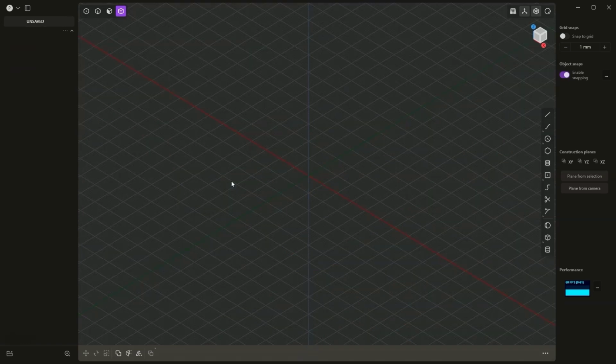The next useful operations can be the rectangular array operation and the radial array operation. These are operations that easily create subsequent instances of selected elements in a specific manner. Regarding the rectangular array, it works in such a way that we can create a copy of the selected element along one direction and along the other direction. I will create a simple cylinder at the origin of the coordinate system with any dimensions.